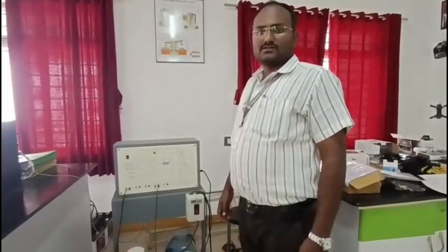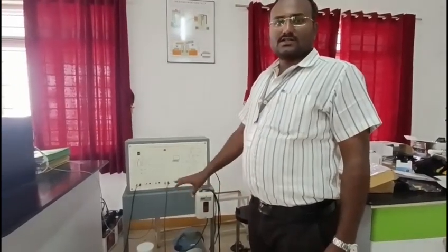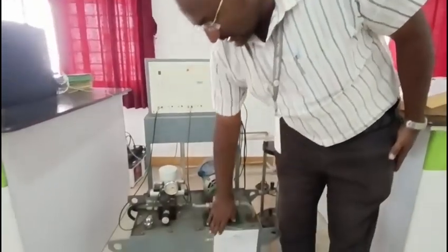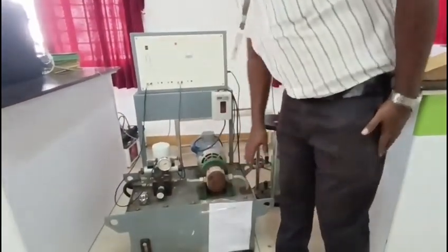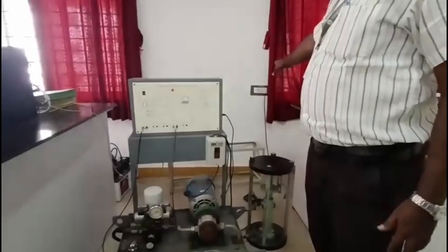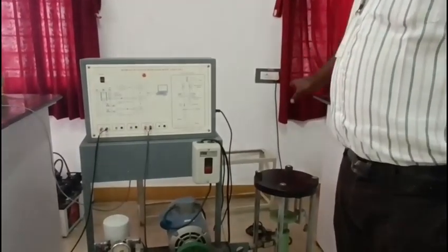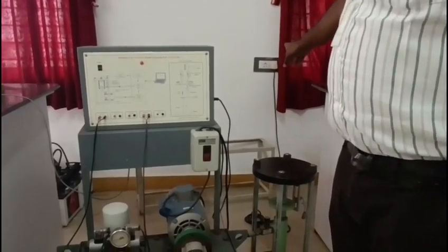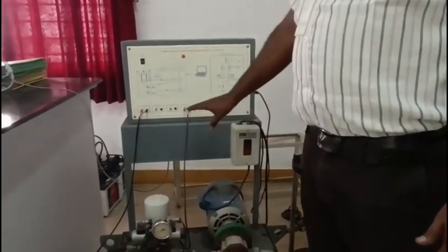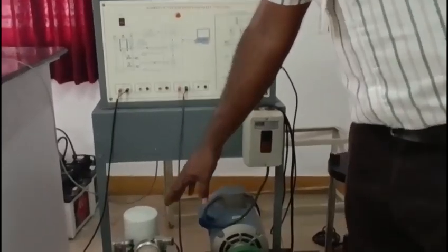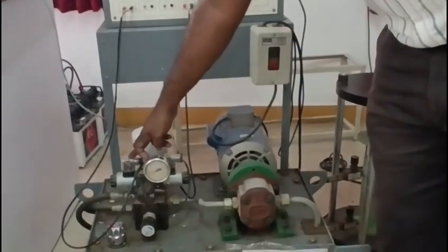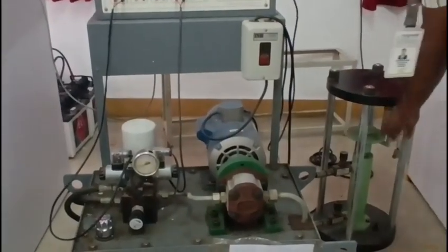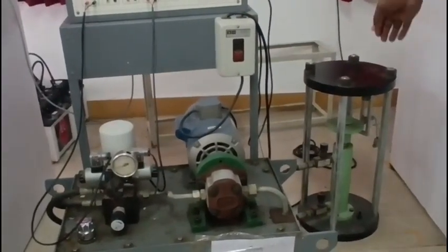The procedure for the hydraulic circuit is, first you have to check whether all the wires are connected or disconnected. You have to thoroughly check, and then check the oil tank for any oil leakages, and check that the plug and wire are properly plugged in. You have to ensure all the wires are properly connected. Then you turn on the power. Then you have to check the connections. This direction is the forward solenoid and this direction is the reverse solenoid. First you move the cylinder in the forward direction, then in the reverse direction.